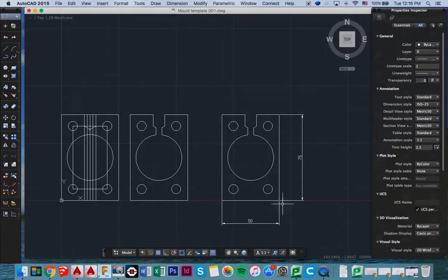See how it's 50 millimeters by 75 millimeters, the same as the aluminium jig we've made. It's got 8 millimeter holes in it. It's got a 10 millimeter funnel here that narrows down to 5 millimeters, and then a 40 millimeter circle here.